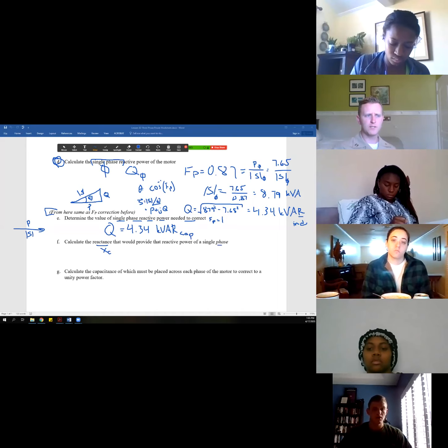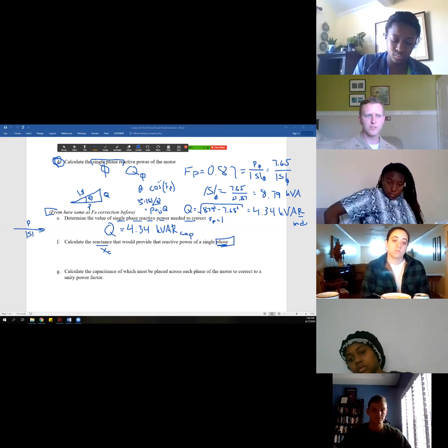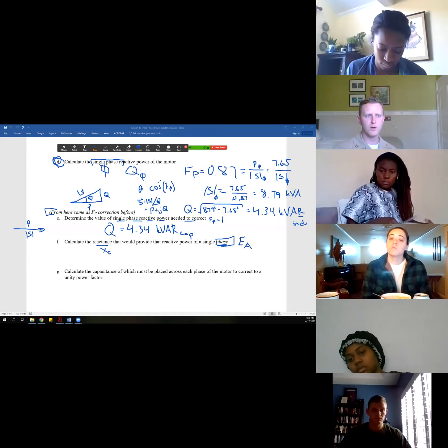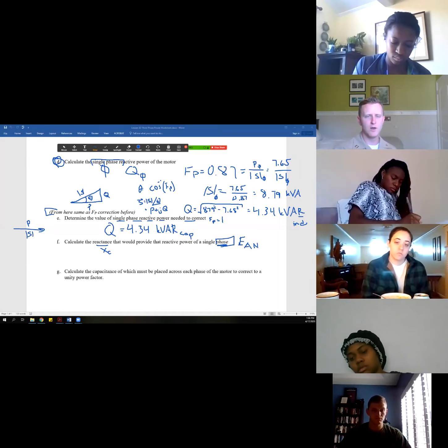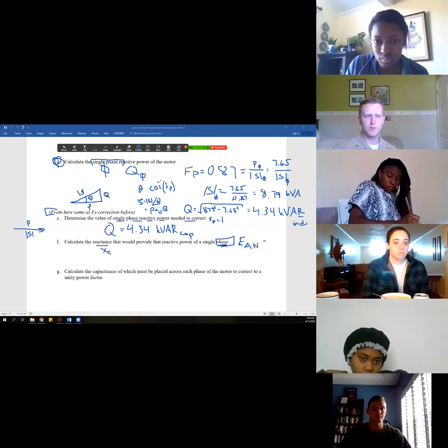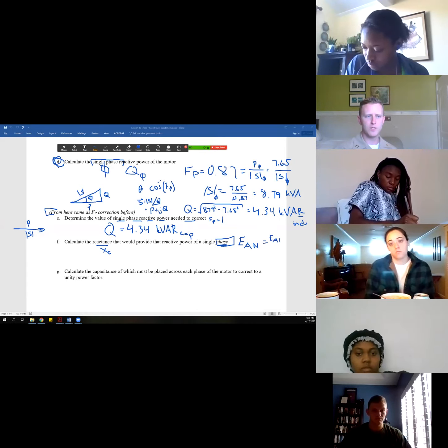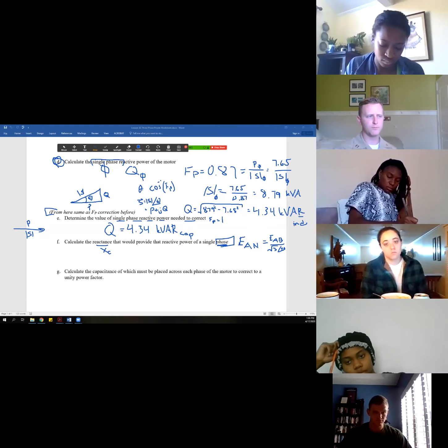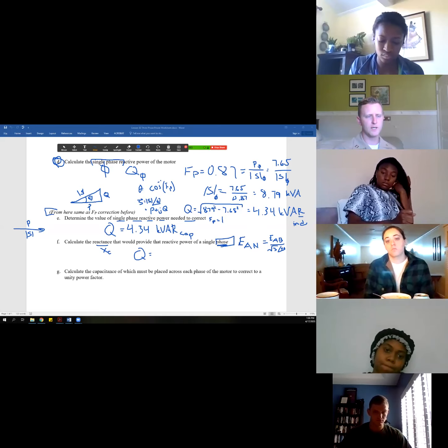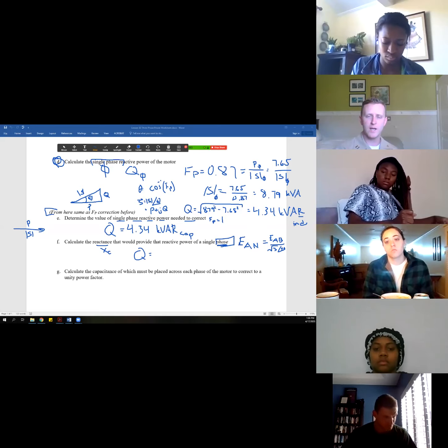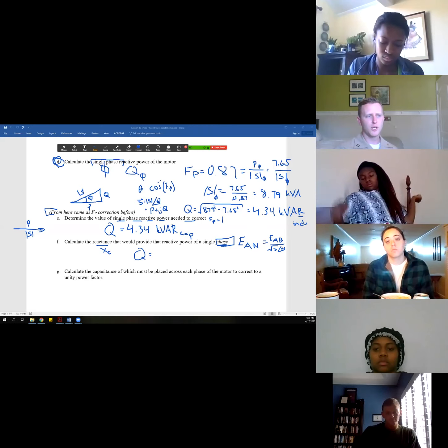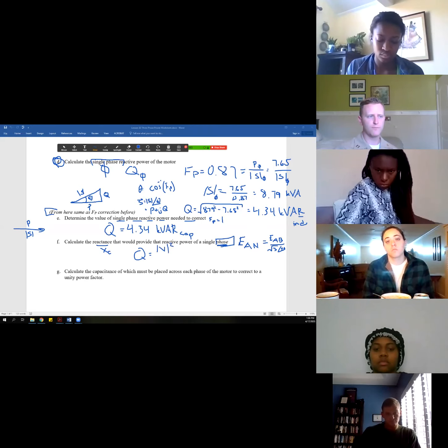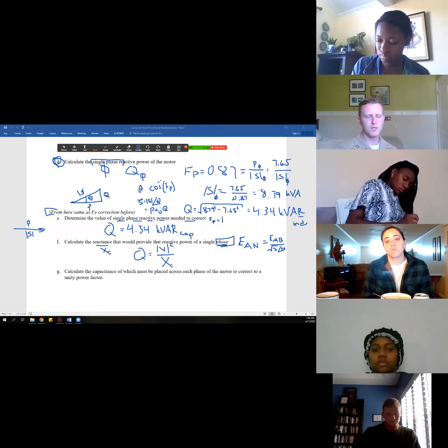And the other thing is that it's of a single phase. And this is maybe the one thing that's different about this three-phase power, is to make sure that we're talking about the phase power, the power of a single phase, which is EAN. We were not given EAN, we were given EAB, right? So EAB is going to be divided by root 3 angle 30. But actually, let's put in the formula real quick, and then we'll discuss EAN. So EAN is of the single phase, so just make sure if you had EAB, you divide it by the root 3. The Q formula for this is the V squared over X, this X being X sub C.